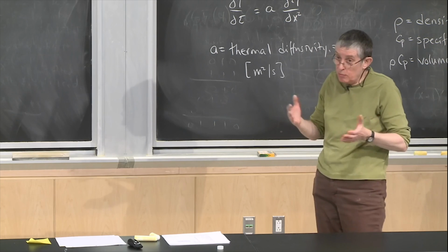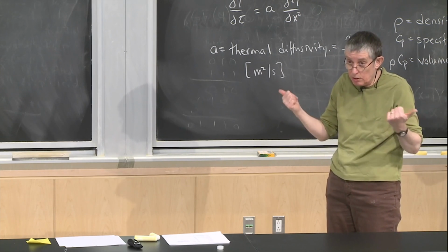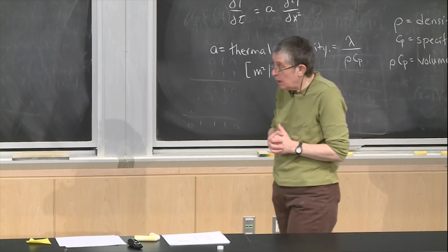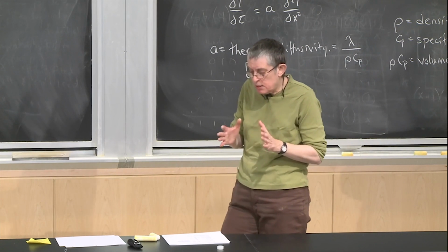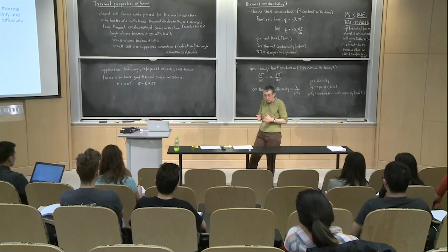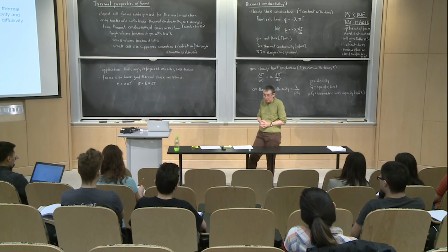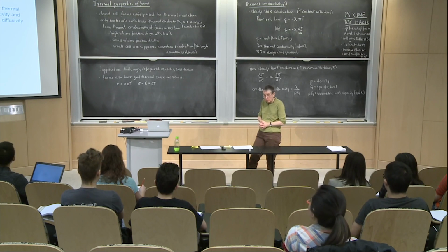So over time, the thermal conductivity tends to increase because you're getting air coming in and the low conductivity gas going out. But I think typically that process takes a number of years. It doesn't happen in a week. But if you're designing a building and you want the building to be there for 50 years, it occurs faster than that. So it's not ideal from that point of view.